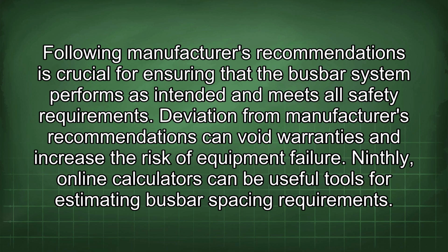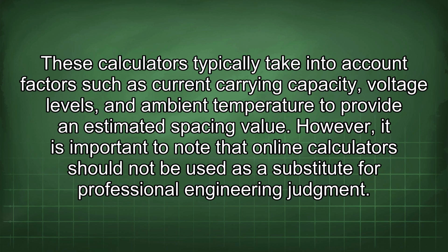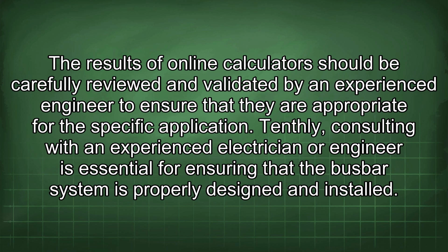Ninthly, online calculators can be useful tools for estimating busbar spacing requirements. These calculators typically take into account factors such as current carrying capacity, voltage levels, and ambient temperature to provide an estimated spacing value. However, it is important to note that online calculators should not be used as a substitute for professional engineering judgment. The results of online calculators should be carefully reviewed and validated by an experienced engineer to ensure that they are appropriate for the specific application.